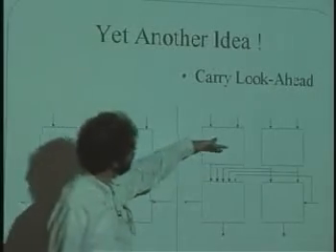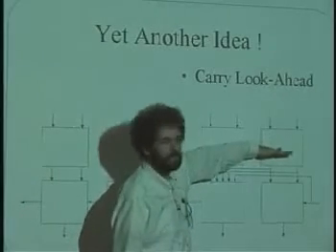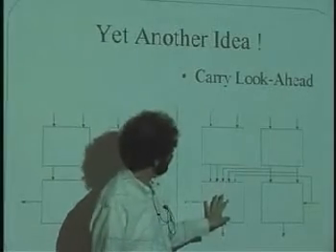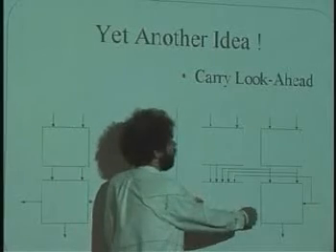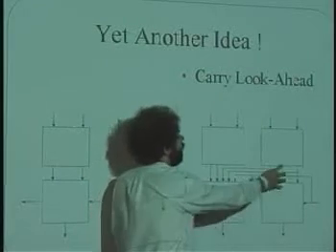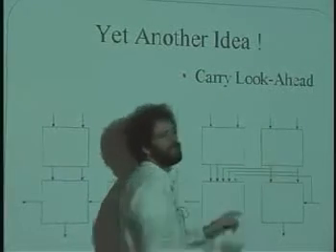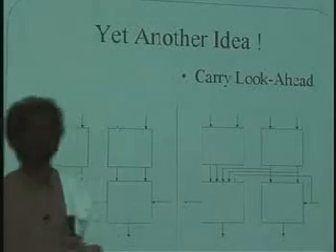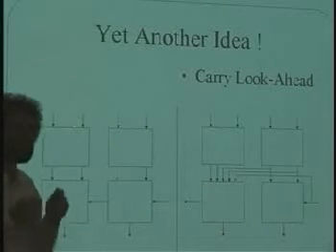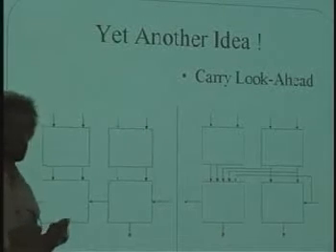And remember, all of these actions occur in parallel at the same time, so if I'm willing to expend some extra hardware over here, I can look ahead at G and P from lower stages to see whether or not I should actually do it. Now, what am I really doing here? Guess what I'm doing, guys?